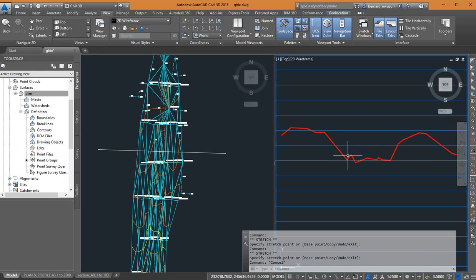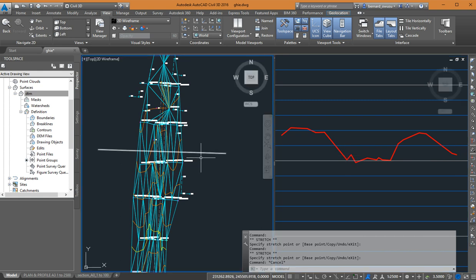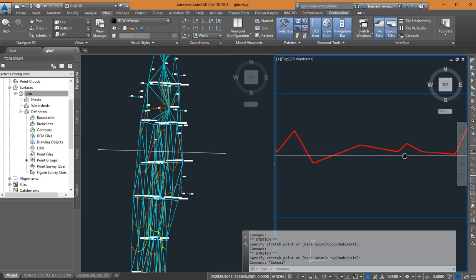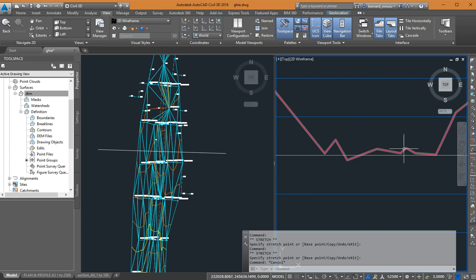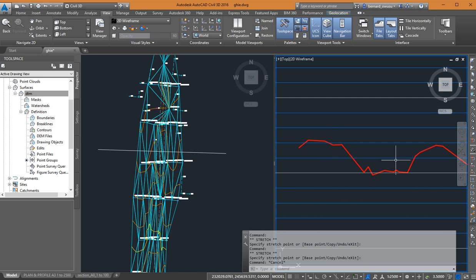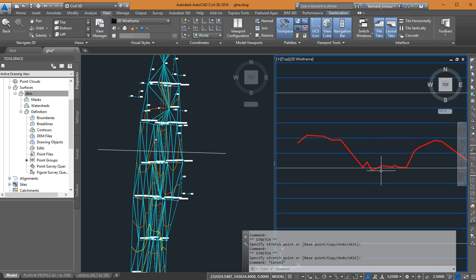Please, are we okay? We are going to use the road edges and the center line as break lines so that we'll be able to refine. Because if you look at what is happening here, it could be that there's something wrong somewhere here. Because you cannot have a road like this. It's likely maybe this one ought to go straight or something. But we can see that this place is like in an embankment. I mean, in a cut.